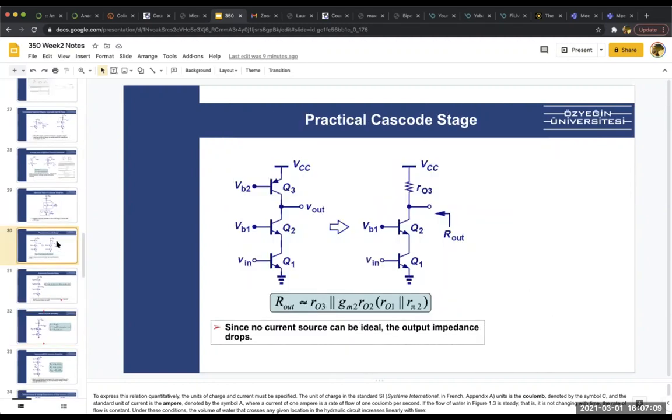The circuit can be a little bit more complicated. So what if we connect the circuit to another circuit at this node? When you draw the small signal, you'll see that you treat the cascode like one arrow here. You already know how to solve it, but now you also need to solve this R so that R1, and let's call this R2, become in parallel.